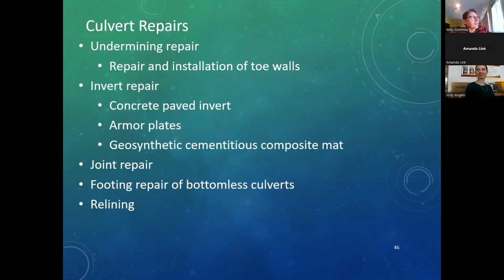With animals taking up residence, I don't know how often it is. My experience has been with beavers clogging culverts with running water. And then the ongoing issue we've had is with under drain outlets, where those daylight, and you tend to get rodents moving in there, clogging up the under drain.